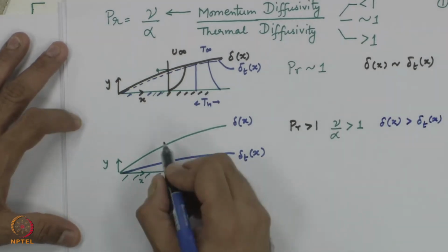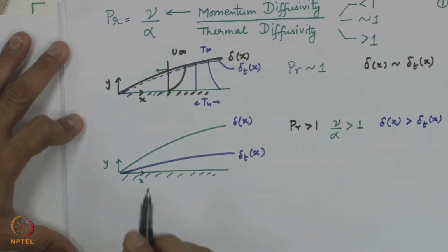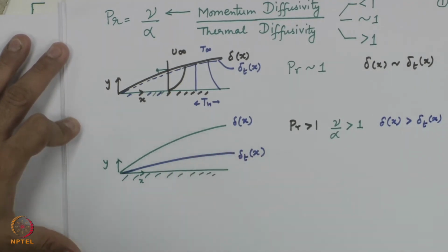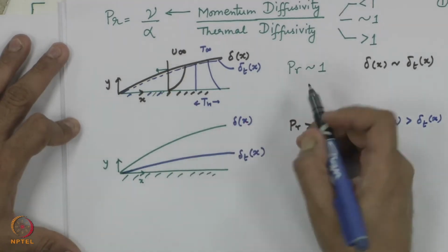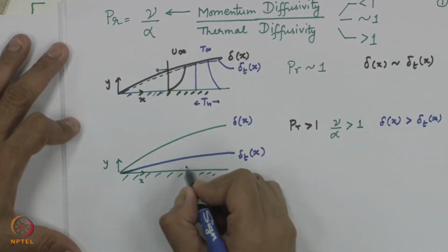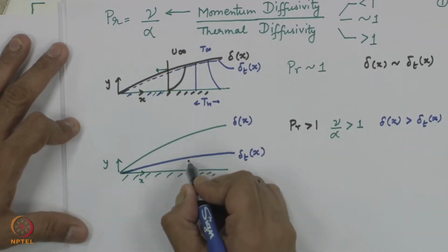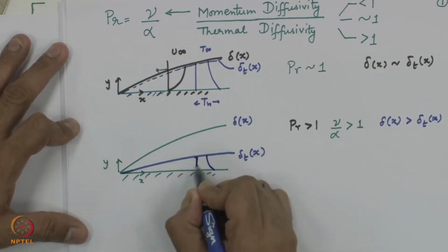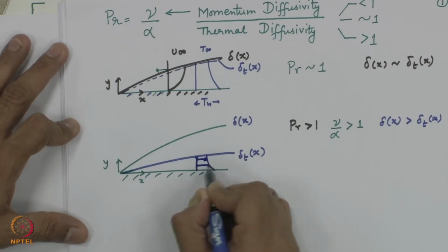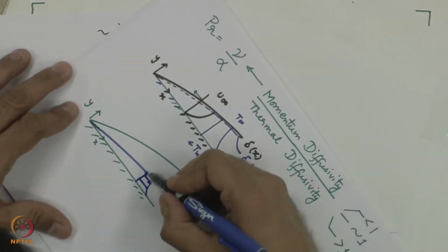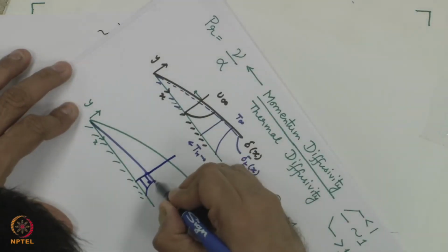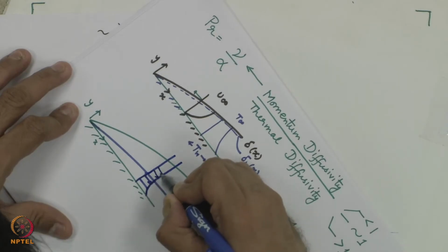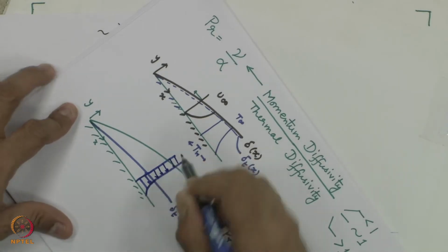Now, if I were to draw the velocity and temperature profiles, temperature, what is the boundary layer? It is a demarcation of the region where the temperature starts to become equal to free stream temperature. So, here alone we would have variation in temperature, only in this part, and all along after that it's a constant value. This is all T infinity.